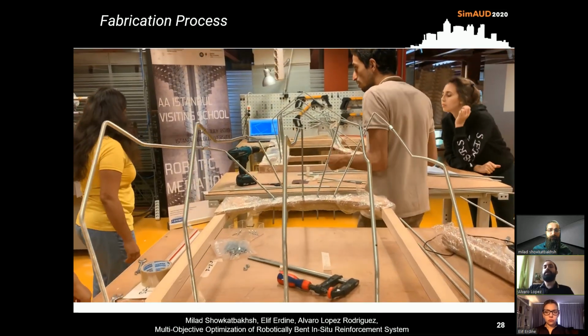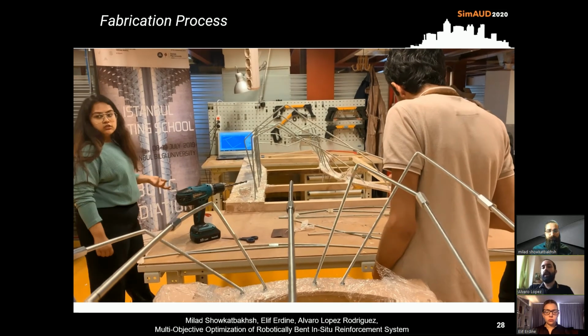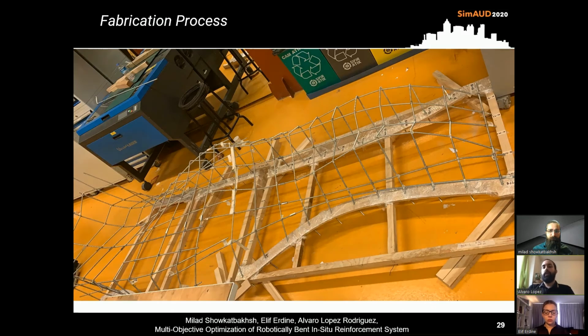This assembly process was made out of a series of wood frames where we were locating all the bent rods in a specific position due to the marking. So they were ready to have the mesh applied for the concrete spraying process.